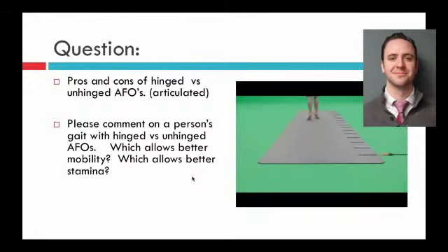the CMT patients would break the bar right out here, or they'd come back a few months later, and this very nice looking spring inside would be in tiny little pieces, looking like confetti. So we started to look for the dynamics more in the material, and that's why we worked more with carbon fiber bracing versus getting the dynamics from the hinges, because the failure rates were pretty high. Plus, the other disadvantage to hinge systems is the bulkiness.